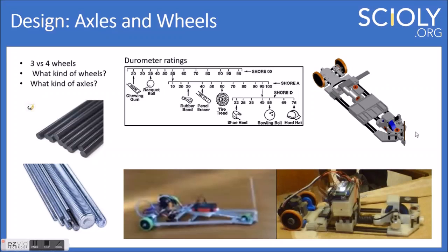If you push against them, you can definitely feel a difference between the 30A and even the 40A. The advantage with the softer wheels comes when you have a lighter device and you need more grip. If you're going to have a smaller normal force, just because the mass of the device is smaller, you're going to need a higher frictional coefficient to compensate for that.